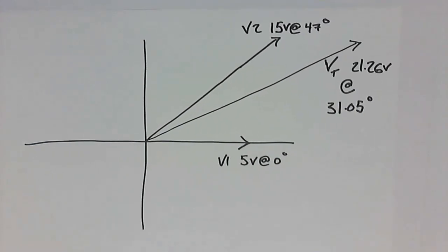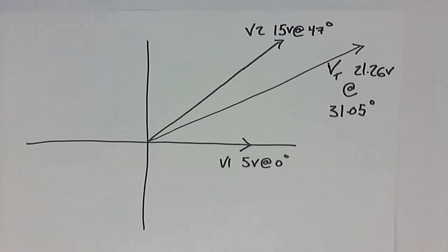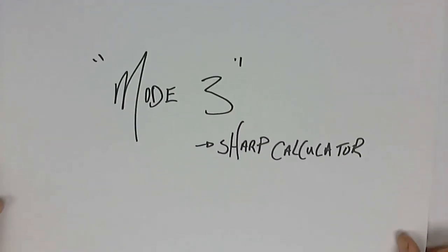All right, so we've looked at the longhand method. It's pretty straightforward. You simply need to keep track of all of your numbers. The main problem with the HV table is that people will inadvertently write down the wrong numbers because there's a lot of numbers you're writing down, right? There's all the horizontal, all the vertical, you're working out the hypotenuse, and then you're also working out the angle.